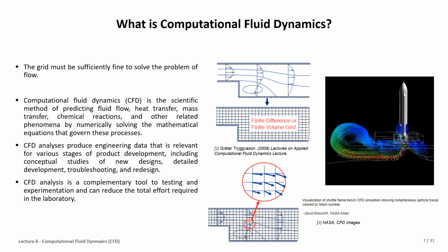Here in this slide, you can see an example of a problem and how it's discretized into very small elements, and then using the finite difference method to solve the problem for the target properties, which could be velocity, pressure, or, for example in heat transfer, the temperature.